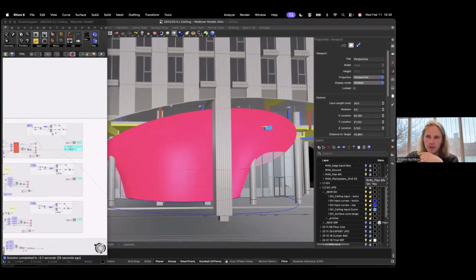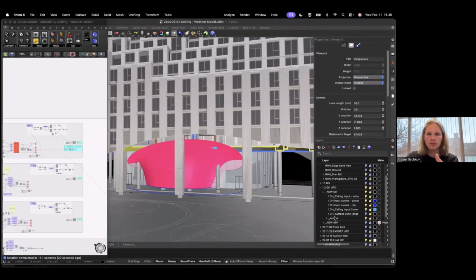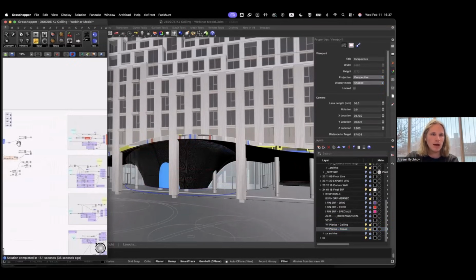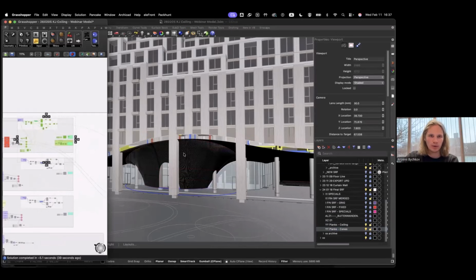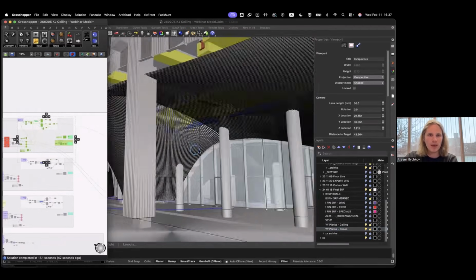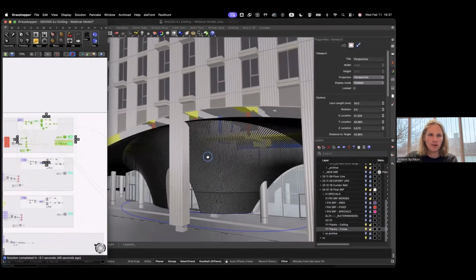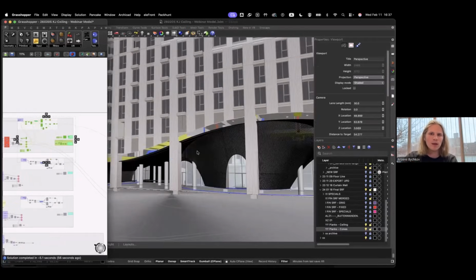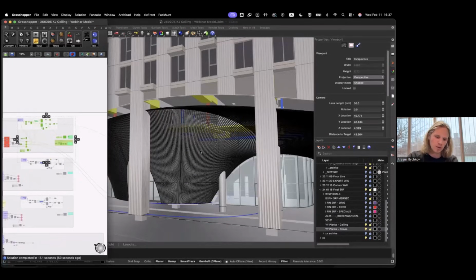So that was part 2. Basically bringing the model to reality and visualizing mainly the planks to be able to see how the actual ceiling will look like. So not only the surface, but also the planks, and to later also provide the construction team with the guidelines of how we would like it to look like, where the dip should be, what are the crucial points in terms of intersections, also intersections with installations, and to also be able to inform the construction team regarding the curvatures, so that both us and them are sure that the design that we made is actually buildable, so that we don't have to ping pong these issues to each other.